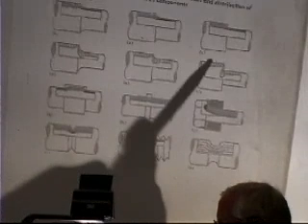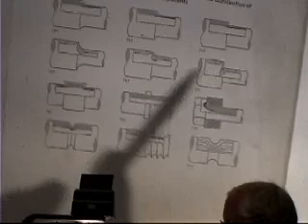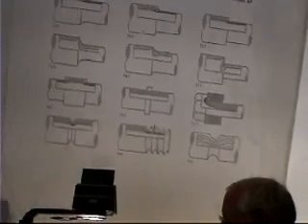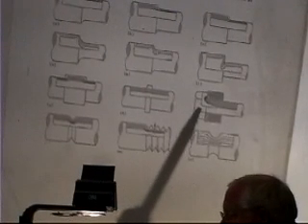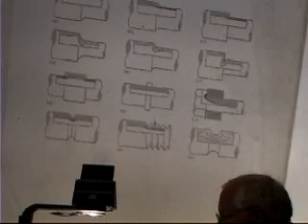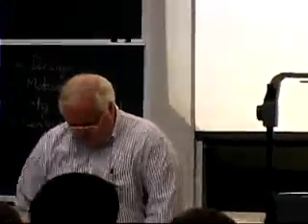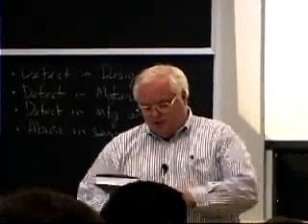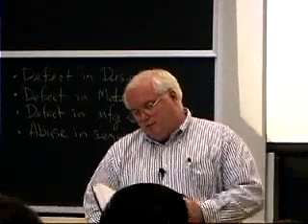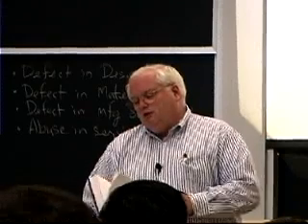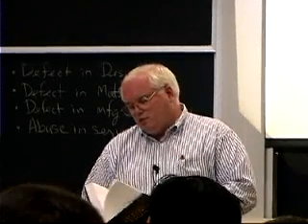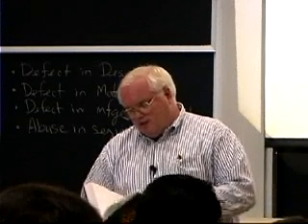So anyway, this is actually a plot of the stress, and you get a stress here and a stress here, but you get a big sharp stress here, and you can decrease that concentration over here. This is a head of a bolt showing the stress concentration, just a bunch of different geometries. Whenever you have a change in section, and just like I showed you the book on fracture mechanics, there are whole books. Also, this is only in the 2nd edition, but this book goes back a long time because people don't do stress concentrations anymore. This was the way they dealt with things back in the 40s and 50s.